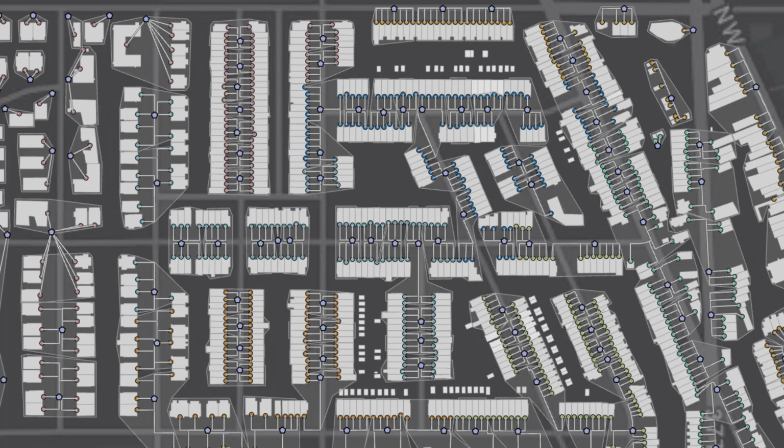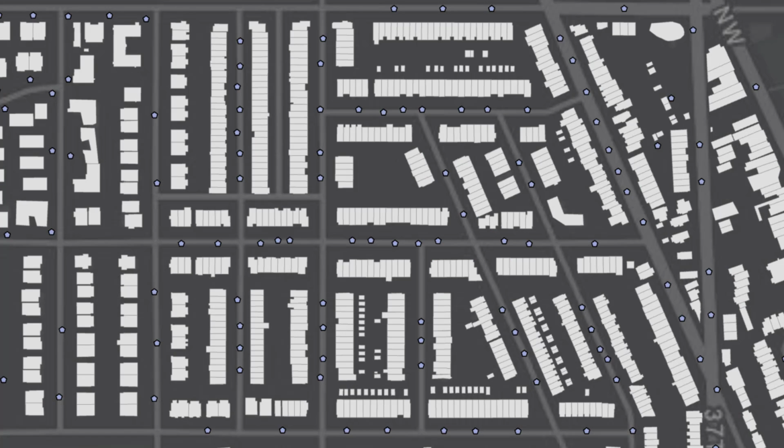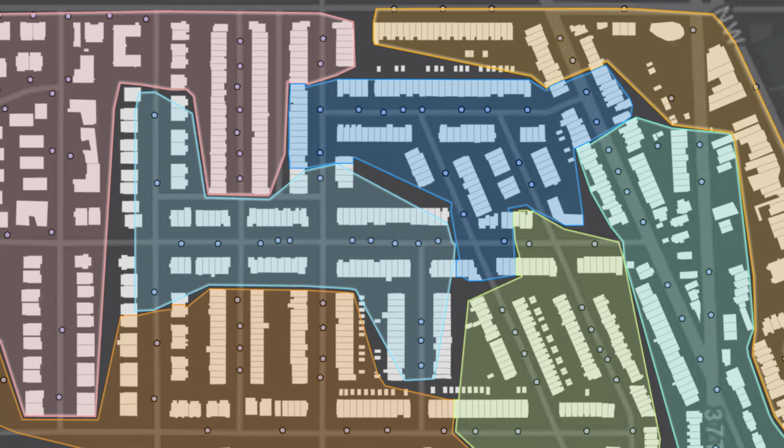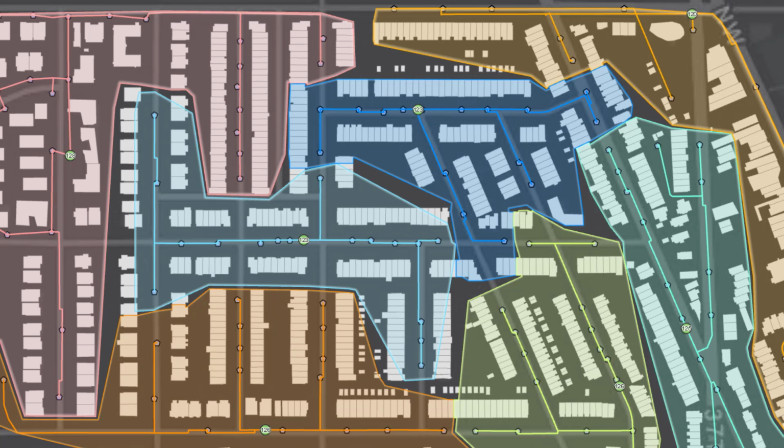When all service locations have been clustered, the layer is finished. Comsof Fiber Designer moves on to the next layer up. The points which were providing service in the previous layer are now the points to be provided service in this new layer. The cycle repeats until the central serving point is reached.